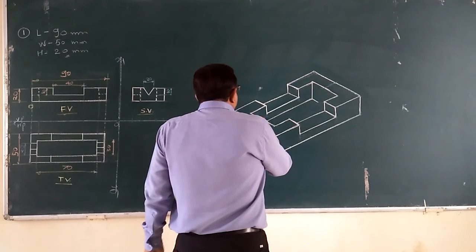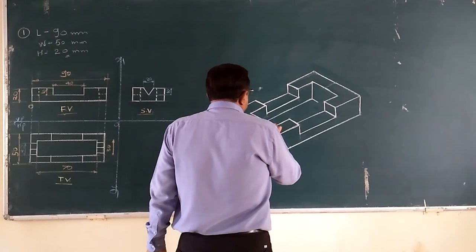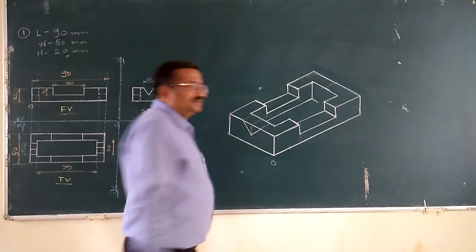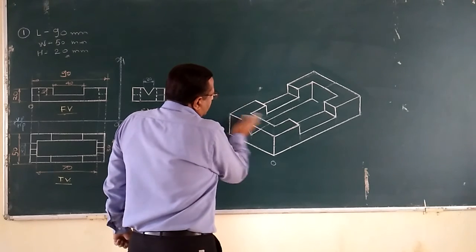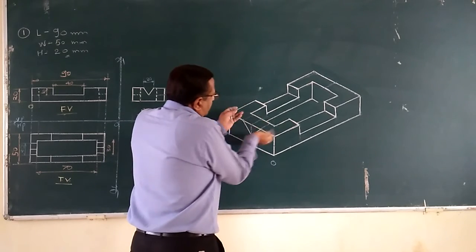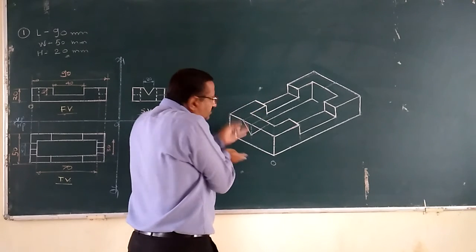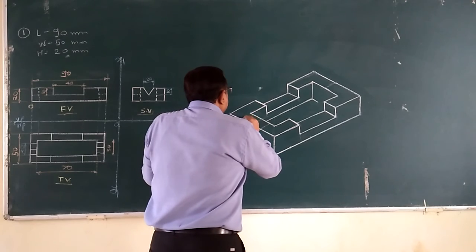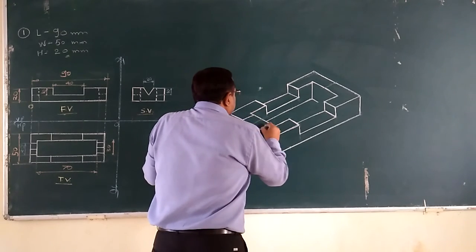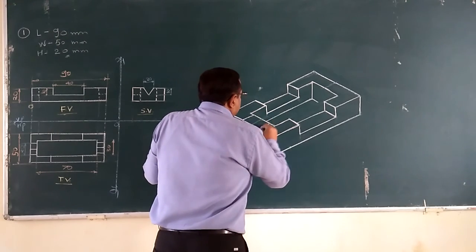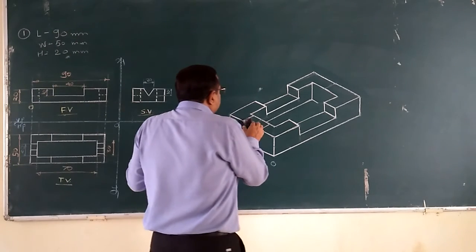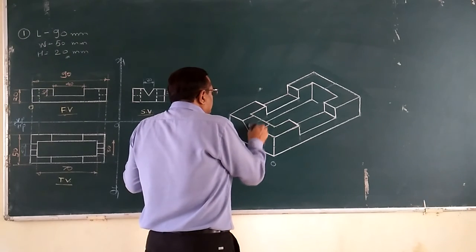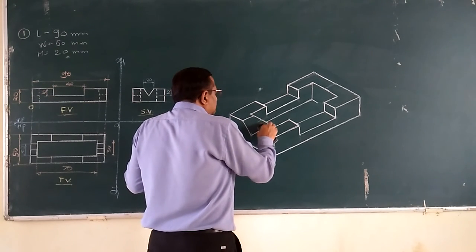Now, you have to mark on this wall the same thing. Draw the lines straight. What does it mean? I am marking this by saw, this part, this part, this wall by V notch. In this way we have to cut, and we have to remove this much part, so that only this much will be retained with us and the remaining part will be removed as a V notch.